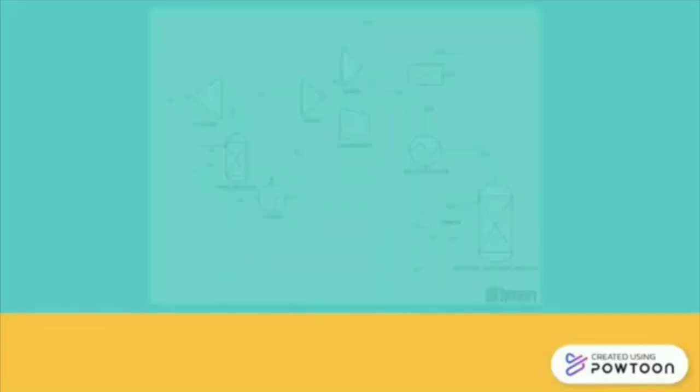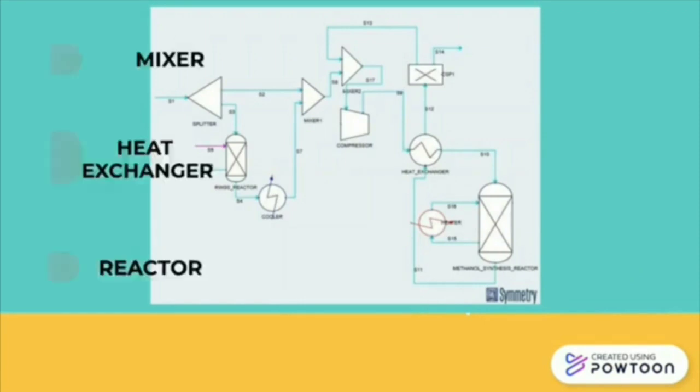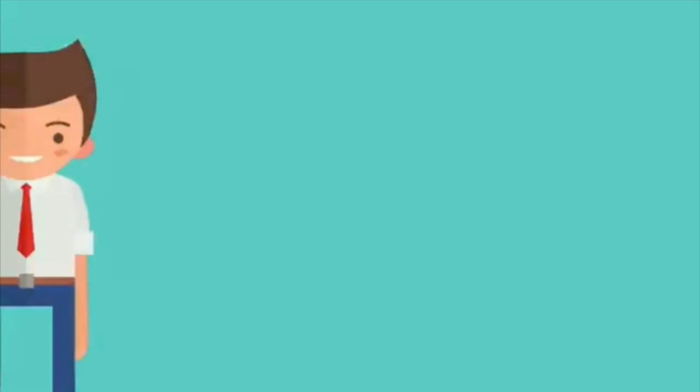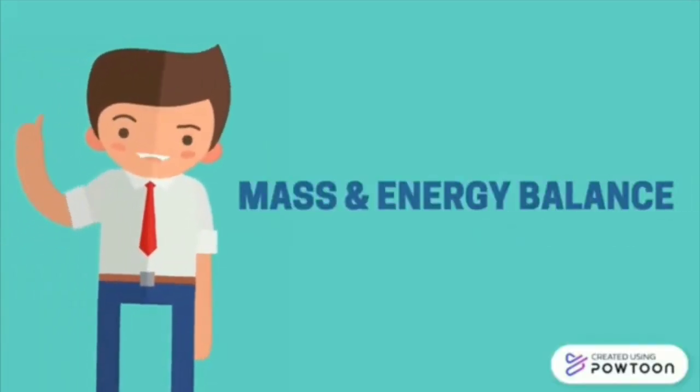Firstly, a process flow diagram should be drawn, which is a graphical illustration of the major process units, piping and process flow paths. The key process units for methanol production are splitters, heater, cooler, compressor, mixer, heat exchanger unit and reactors. Mass and energy balance are crucial tools used to ensure efficient and safe operation.